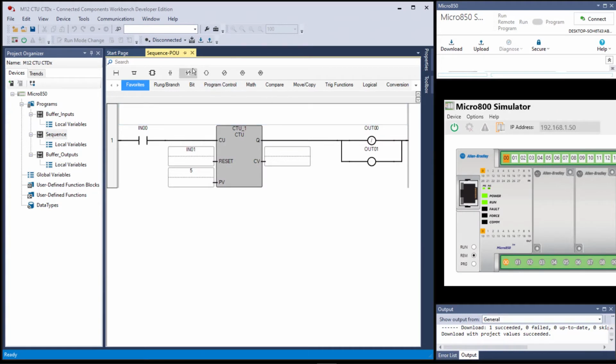Okay, now we're going to connect, but you got to make sure input 0 is on, because when we shut it down, it lost input 0. Now that to me doesn't appear to be a 100% perfect simulation of a real controller, because if the field device connected to input 0 was feeding voltage to that screw terminal, when this comes up and running, that would still be on. Now let's connect.